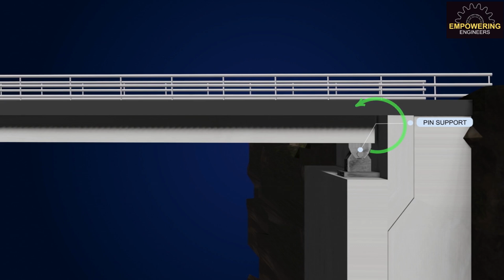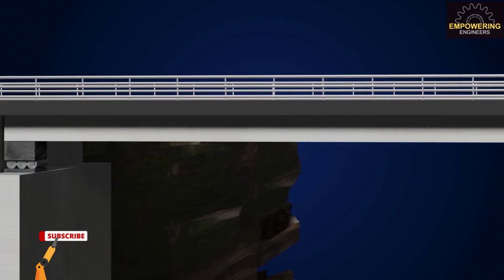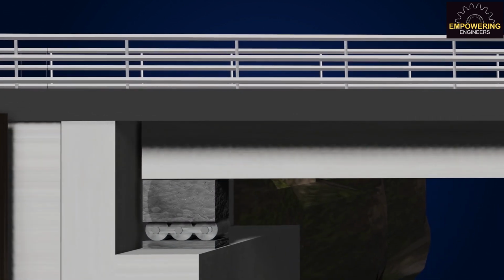Materials such as steel expand at high temperature and contract at low temperature. These environmental factors have a greater effect on long-span bridges. As a result, bridges must also be adjusted axially along their length. Roller supports are used at this location.